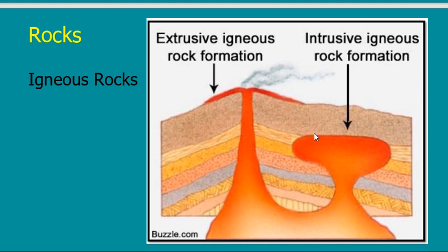If I penetrate with the borehole deeper, I will reach, maybe, a very soft soil. It's not important if I'm standing on a big piece of rock, then it is solid. But if below this piece of rock, I have 1 meter of sponge, is it important? Standing on a very big piece of rock on top of 1 meter of sponge, is this a solid foundation? No, it is not a solid foundation. That's why it is important. That's why we are now concentrating on what is important for us as engineers, especially as geotechnical engineers.